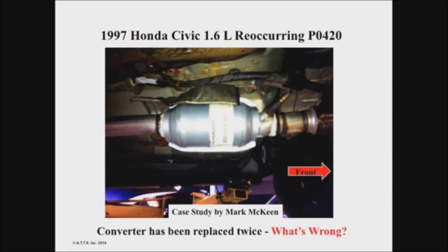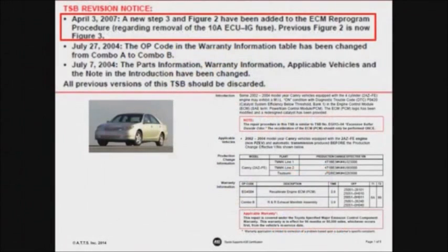Okay. TSBs, we're almost done. Now here's Toyota. You're not going to fix this 420 on this Toyota. You can use the tech stream or use a J2534, go to their site. It gives you all the warnings here, and by the way, don't forget to pull that fuse. There are warnings besides put a maintainer on.